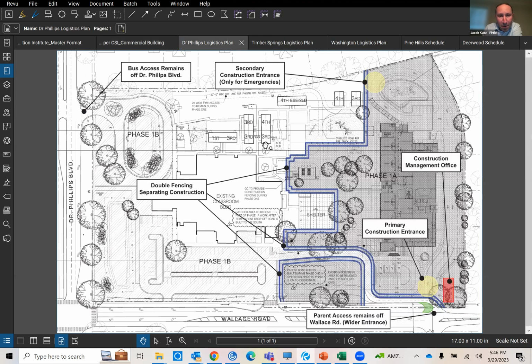But for example, and there are different approaches here to how to do this and the level of information to show, this is a school project once again, and I've used this particular school to show other examples at Cooper City High School, which is the school that I mentor at. But this was a site logistics plan that we prepared. We were building the new building on the right side here that I'm circling right now, while the existing building was being occupied by the students.